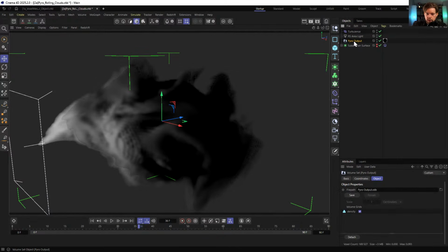Density on. Yeah. Okay. You turn on the density. And now when I made this editable, we get this Pyro object, and it's linking to density. And this is the only way I found that you could actually clone it, because I'm going to select density and detach it. Most people probably haven't done this. I haven't really done it. But you can see I got to actually output my density as a separate channel here. And now it's a standalone object.